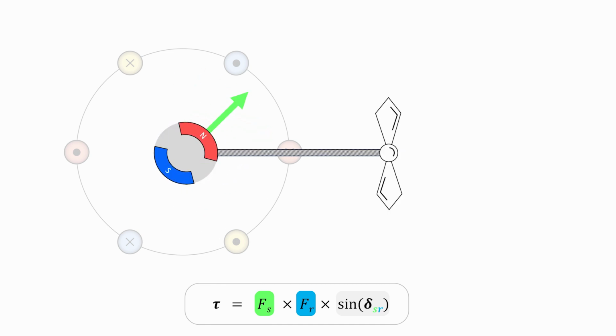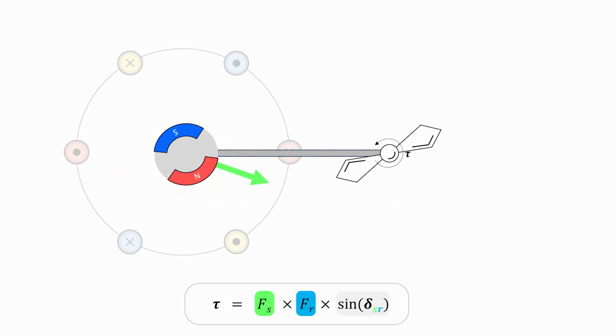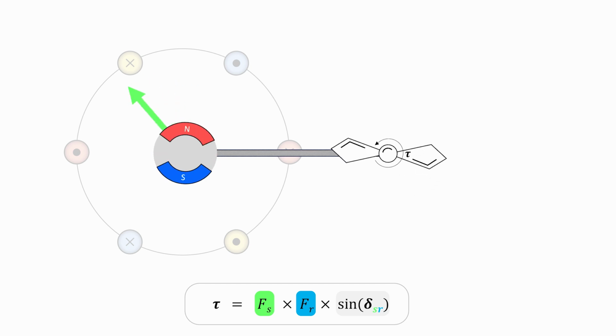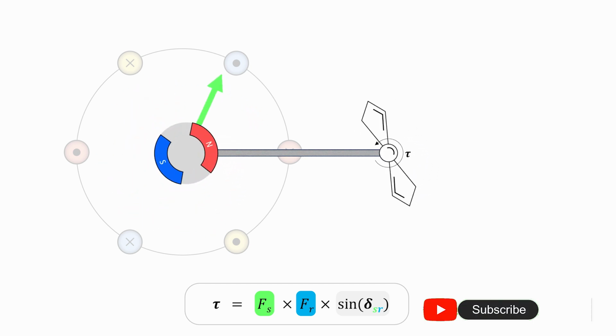When a load like a fan or a propeller is added to the rotor shaft, it demands torque from the motor. The rotor falls back from the stator field to create a misalignment and supply the necessary torque. Any motor supplying torque will always have the stator and rotor field misaligned to generate that torque.